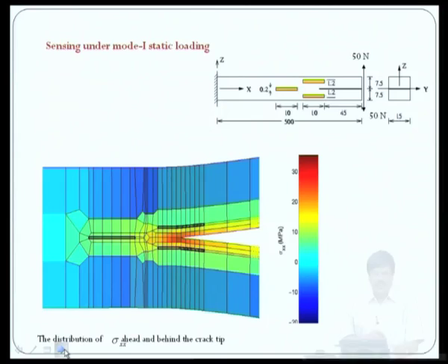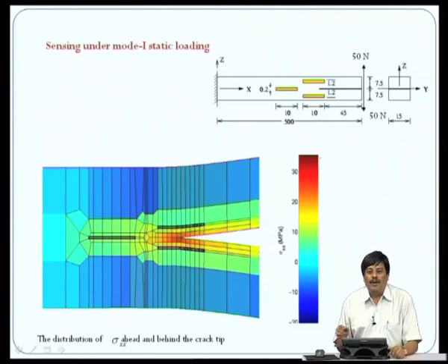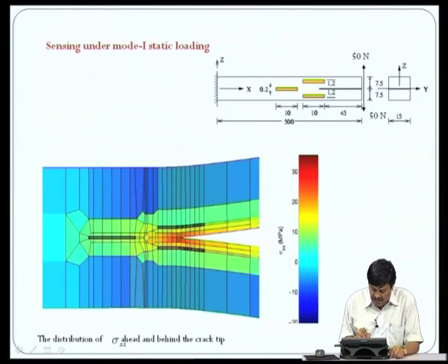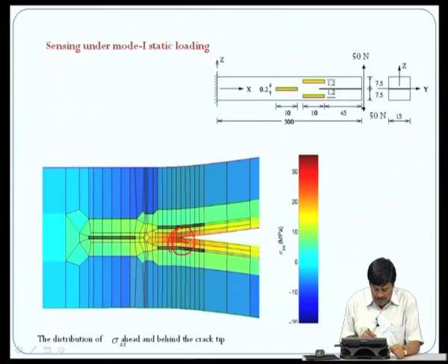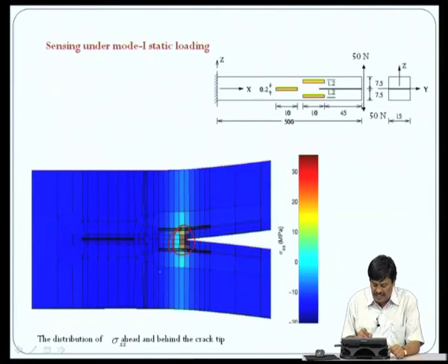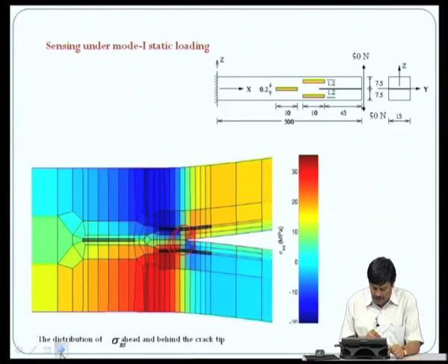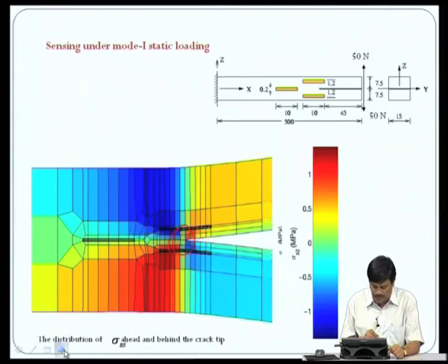So, before doing it, if we model this with our formulated element and predict the stresses, these are basically the axial stresses, and we see that a very high stress is found in this region, which is basically a singular region where the stresses will be very high because the crack is emanating from here. So, we can actually predict the sigma x, sigma z, which is the other stress that is there, also pretty high here, and the tau xy basically.